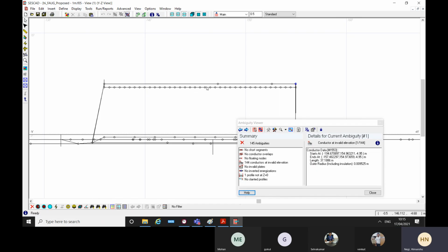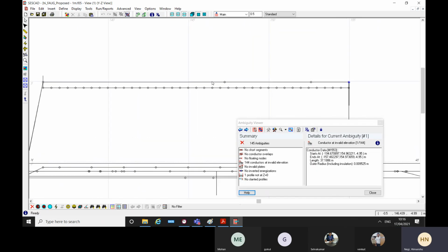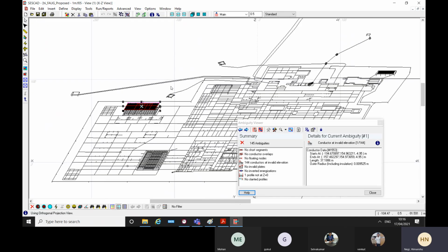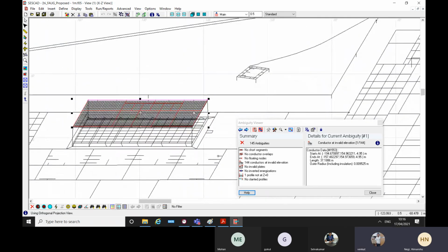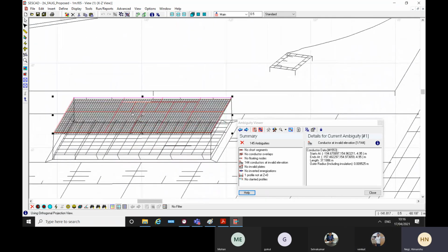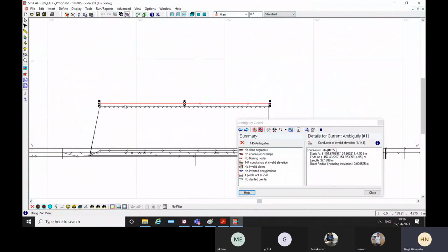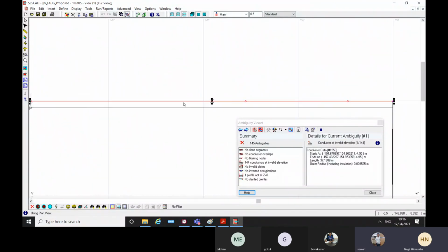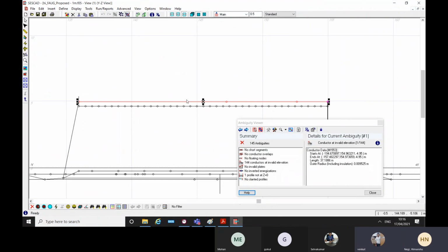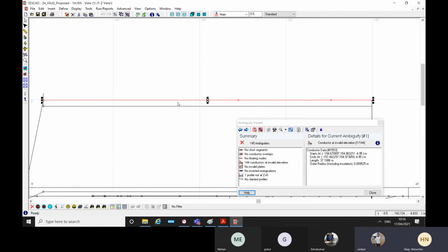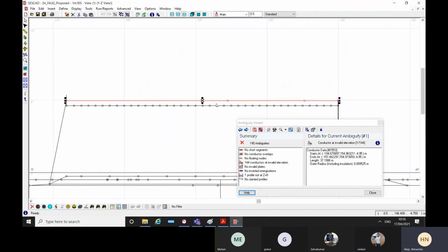Yes. So what happens in the field is that some manufacturers say this copper mat, which you can see on the top now in the 3D view, runs only this much on the GIS surface. Probably you can also see the shape, this is how the GIS will be structured in this area. Manufacturer to manufacturer, they say put this copper mat on the top of this rebar on the final floor, right? And then earth all the GIS on it, right?